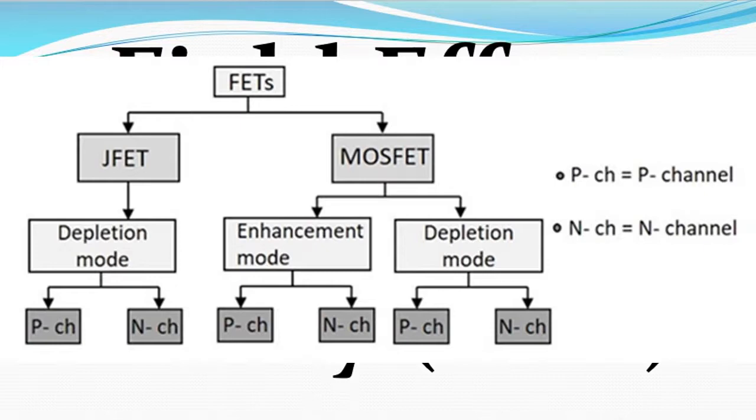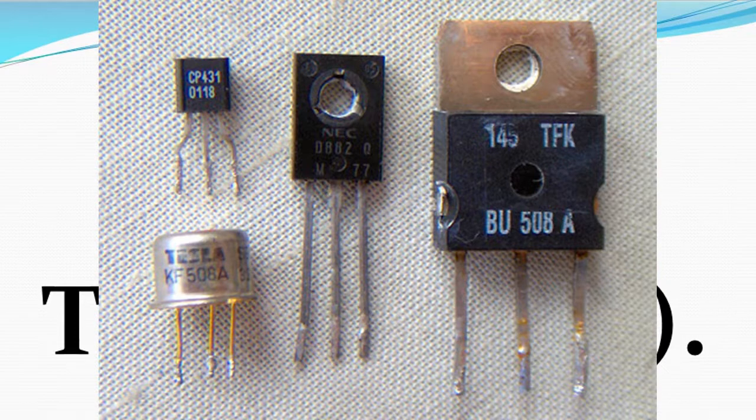I believe that you are getting what I'm saying, because the FET transistor is a three-terminal device, which I have said. I want to repeat that it is constructed with no PN junction. It doesn't have any PN junction within the main current-carrying part between the drain and the source